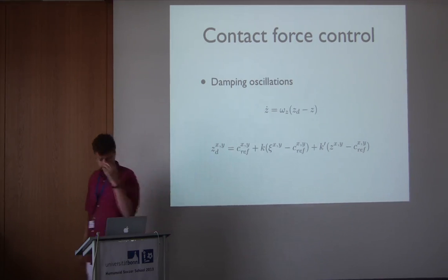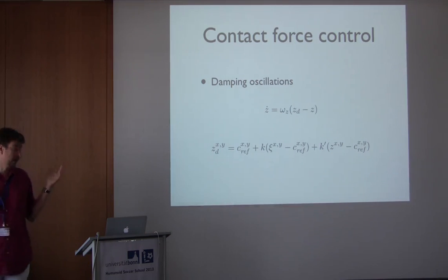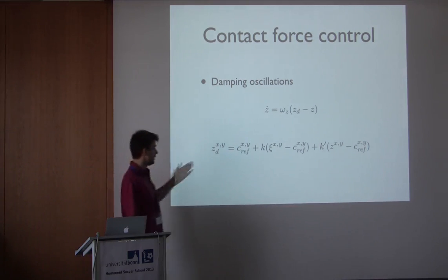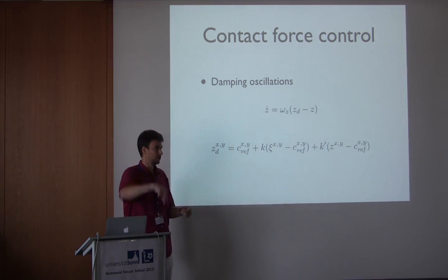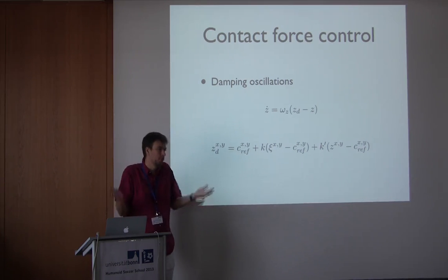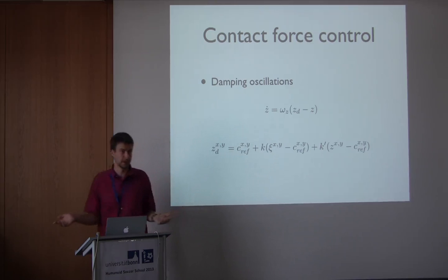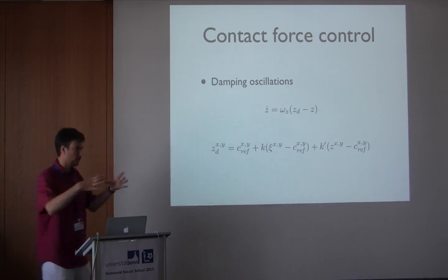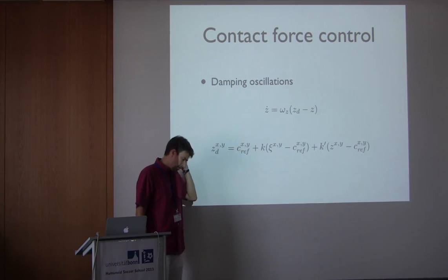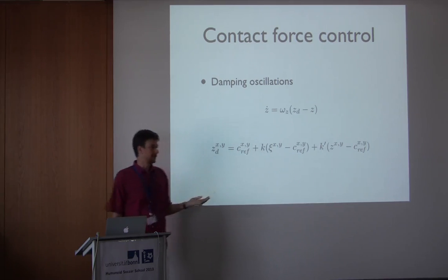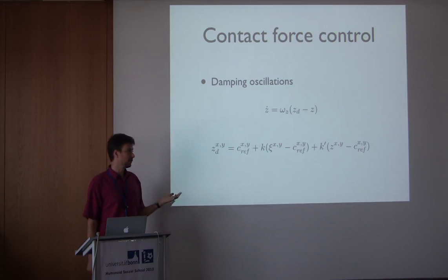What should you do? Of course, and that's what people do so far, you can saturate, say, well, okay, I want to put it there, but it will stay here, because anyway, my support plane is right here, so it should be put here. And then hope for the best. Okay? So you just saturate your controller and hope that it will work very fine. The other way would be to take into account these constraints. But then that falls back to the constraint dynamics that we were dealing with when generating the walking motion.